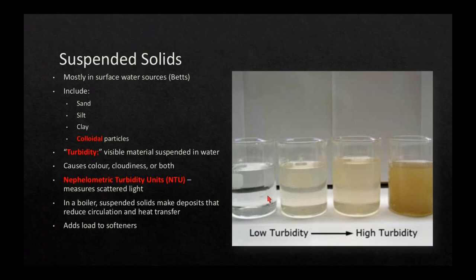So in this slide here, you can see turbidity, right? I mean, it's adding cloudiness and color, and this one here obviously has the most turbidity, and this one here has very, very little turbidity. And we can actually measure turbidity with a turbidimeter, believe it or not, and the turbidimeter is going to give us turbidity in NTU. And people might wonder, well, what the heck does that mean? It's nephelometric turbidity units. You can look that up. I'm not making this up. You can't make it up. Nephelometric turbidity units. So that's why we just say NTU.